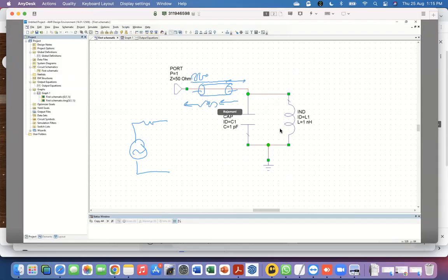And it's going to reach the port again. And remember, the port also has this detector. Maybe the detector is somewhere over here, which is looking at this. And what it is really calculating is what was the amplitude of the wave it sent. So the voltage across these 2 points when it sent the signal, and the voltage across these 2 lines when it received the signal back. And it's plotting that ratio.